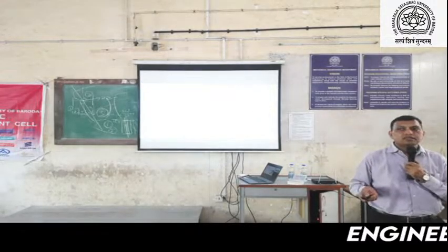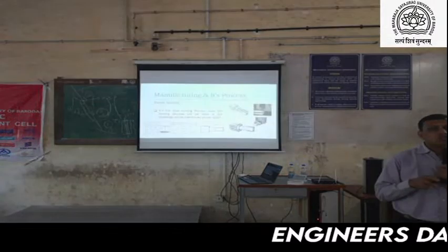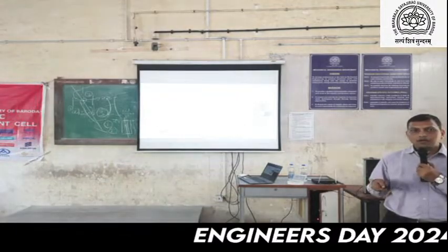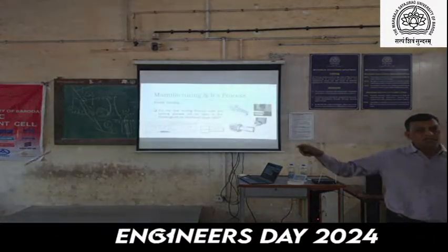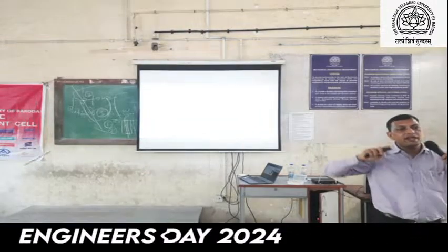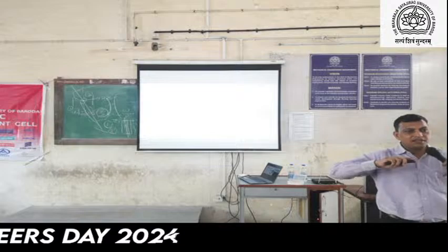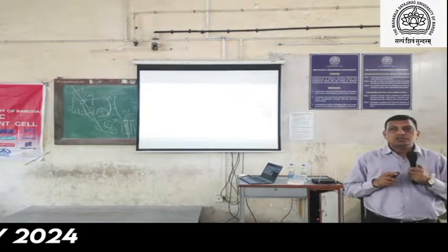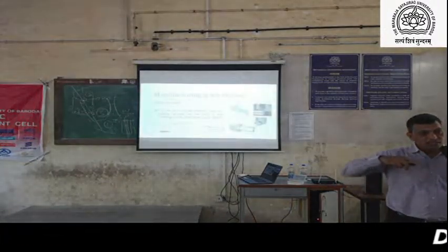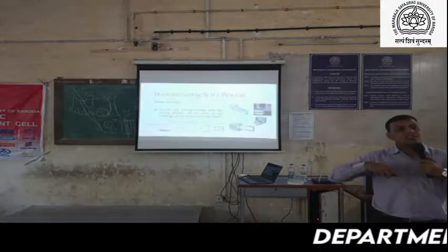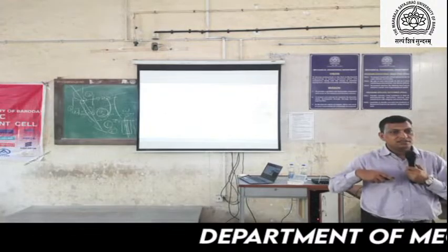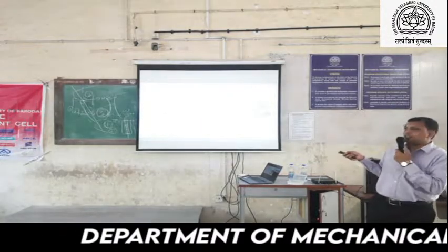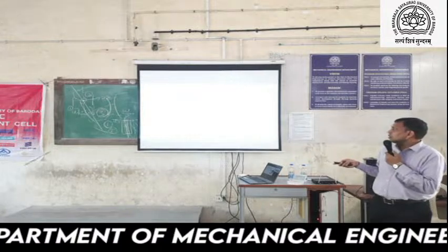After heat treatment, there is some chance of distortion of the material. If there is a long shaft, it can be bent or slide due to heating. So that should be straightened and then the final finish form finalized. So that should be considered in the finish turning.